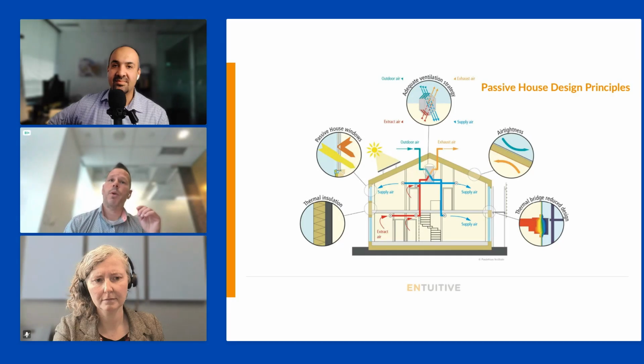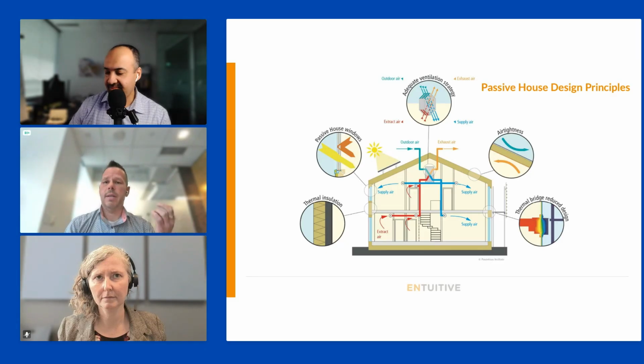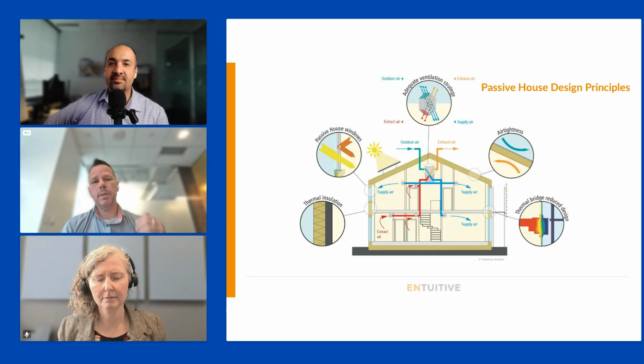In fact, probably one of the most important aspects of good building design and good building enclosure design is focusing on air tightness in design, making sure the design teams are aware of it, making sure your specifications include targets and strategies, making sure that you talk about it in construction, making sure that you assign responsibility to this to someone so that there is accountability. And then we could talk a bit about measuring air tightness as well.